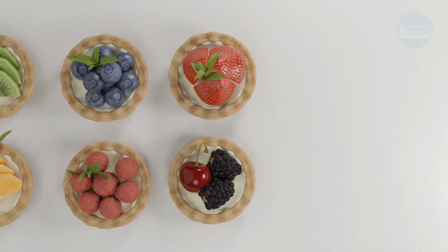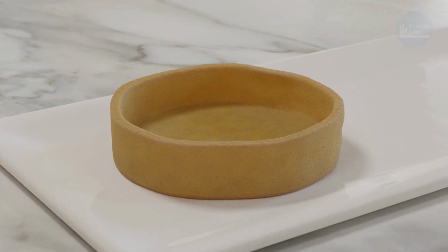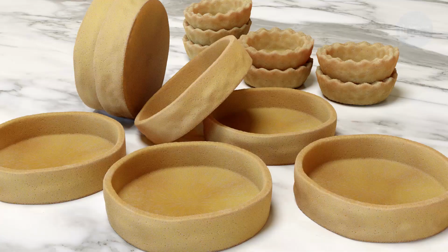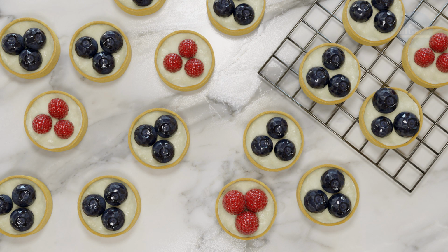And that's it. Tarts, especially the crust, was a pretty interesting material to make, and making the PBR crust was by far the hardest thing to figure out, since I didn't want to just slap on a photograph of a tart shell as my base material. For close-up shots, you'll need a high level of fidelity, both on the tart and fruit. For wider shots, or if the tart is in the background, you can reduce the mesh on the tart significantly.